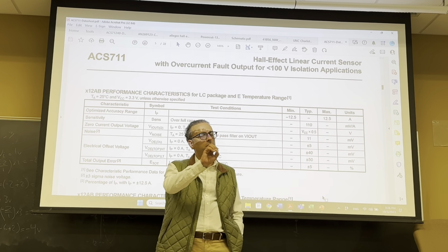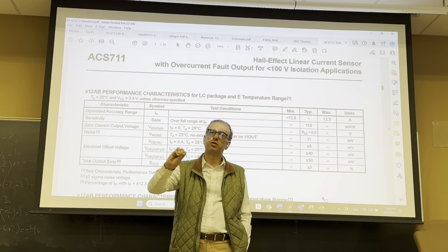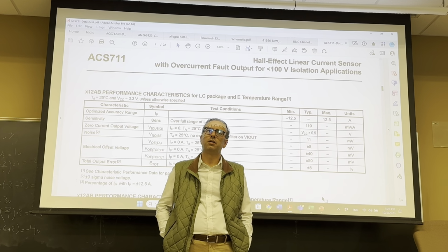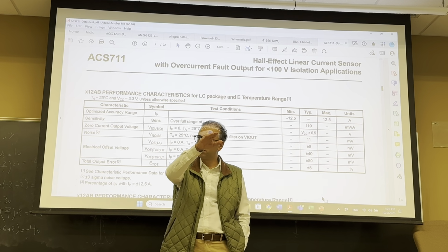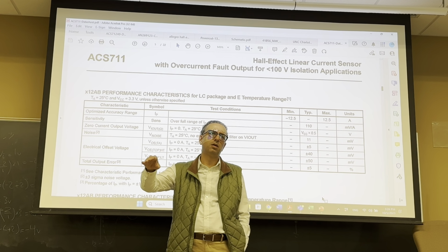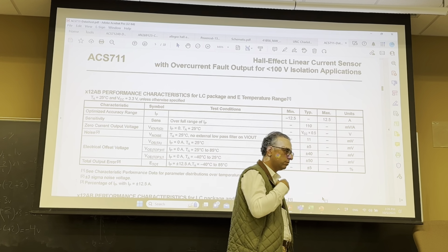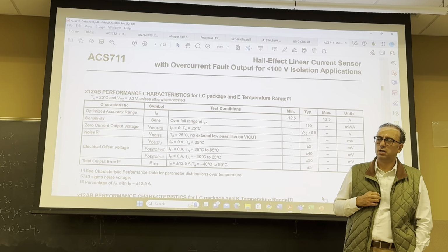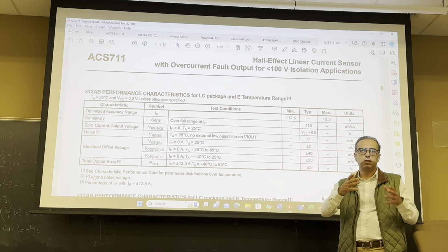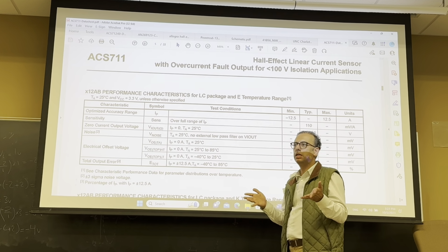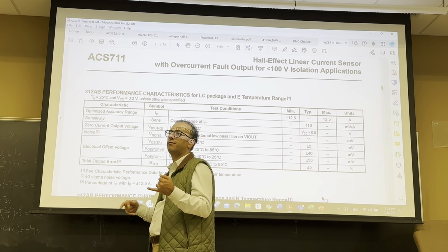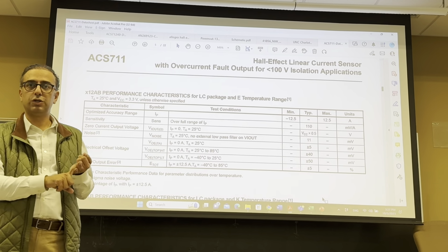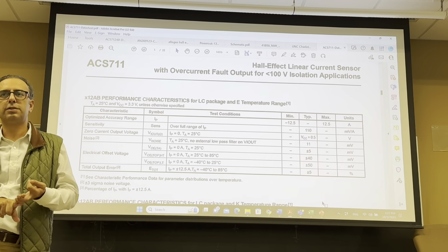Can I input 5 volts output to my microcontroller? No. You have to reduce it to 3 volts, and then you have to worry about that. In other words, the conditioning circuits that you're building consist of gains, filters and buffers.